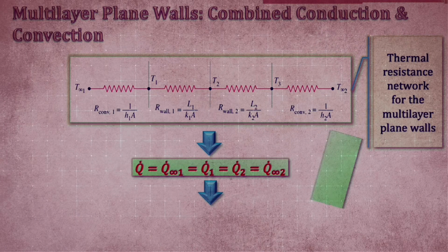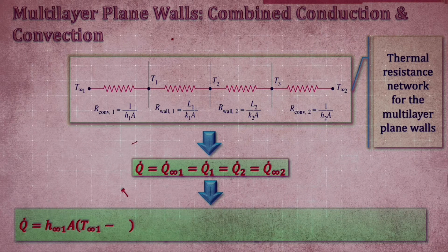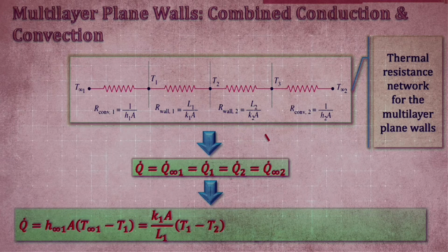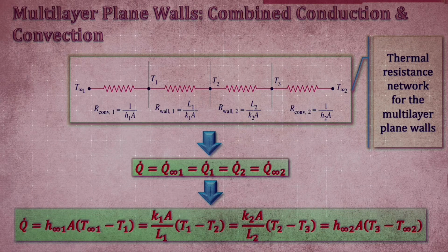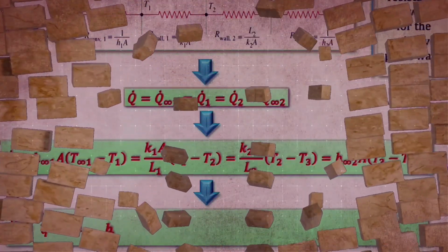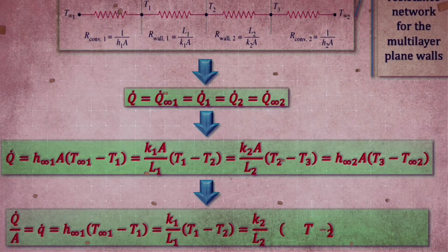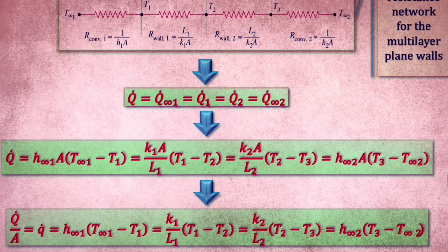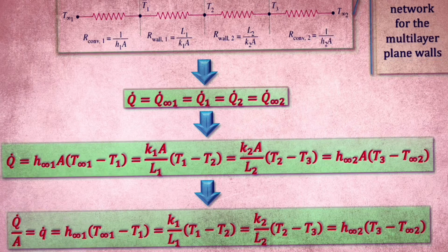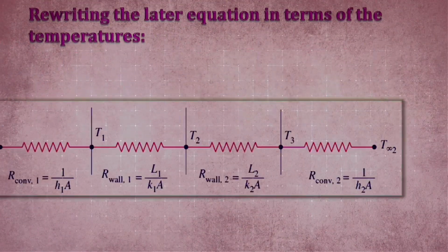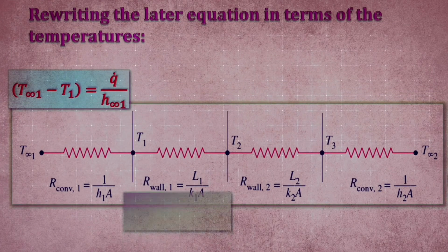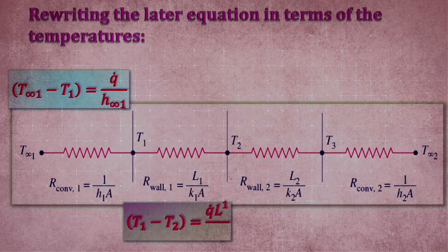The thermal resistance concept is widely used in practice because it is intuitively easy to understand. It has proven to be a powerful tool in solving a wide range of heat transfer problems, but its use is limited to systems involving steady heat transfer with no heat generation, such as resistance heating or chemical reactions within the medium.